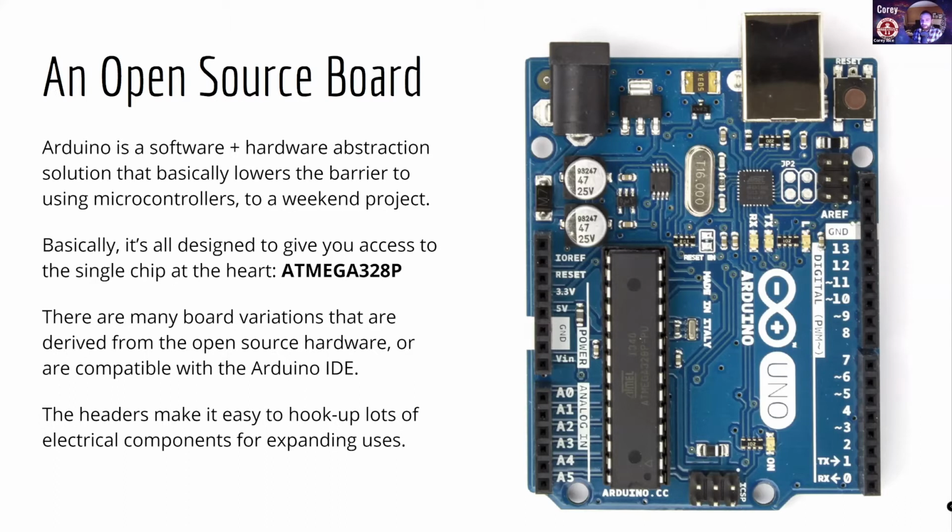And the entire board is all there with all those components, all the things that you see on it, basically just to get to that one chip, the big black rectangle, sort of off center from the middle of the chip. This ATmega328P is the logic that everything on the board is subservient to. It's all just trying to give you access to the pins on that chip, or set it up so that it can talk to your computer really nicely, or let you reprogram it, or see if you're transmitting, receiving, giving you some steady, consistent timing.